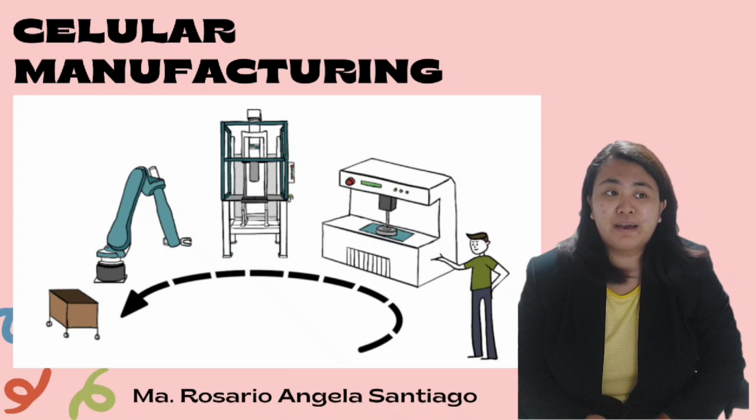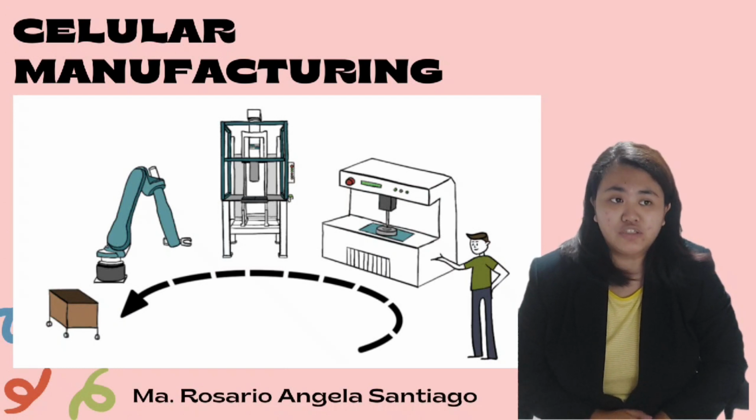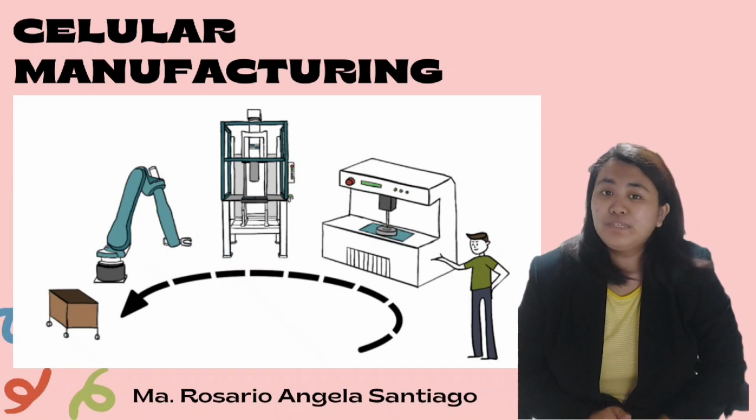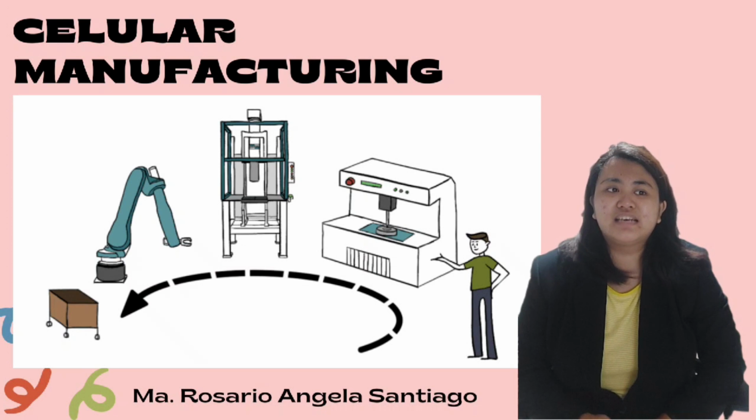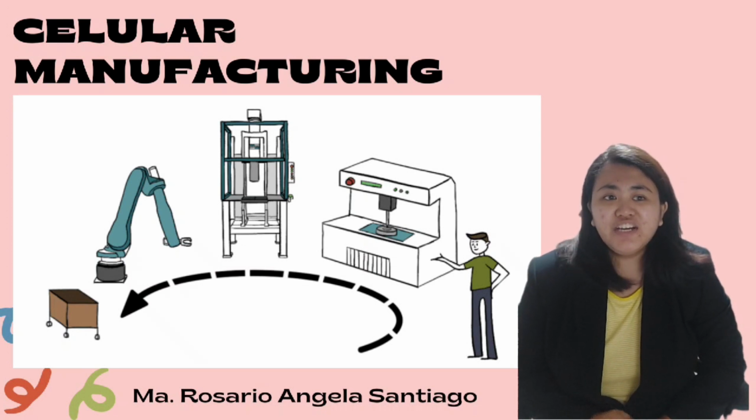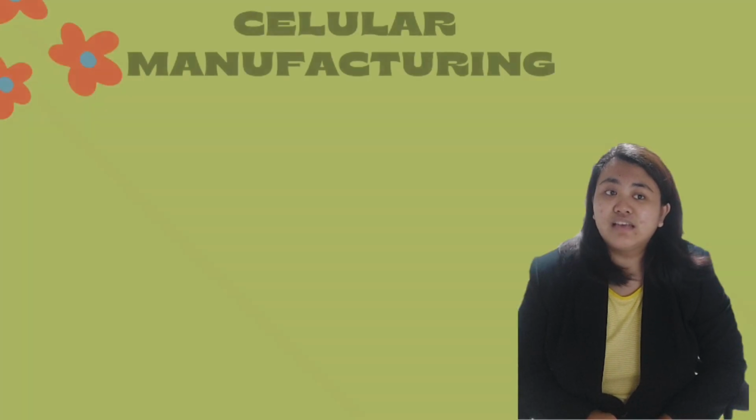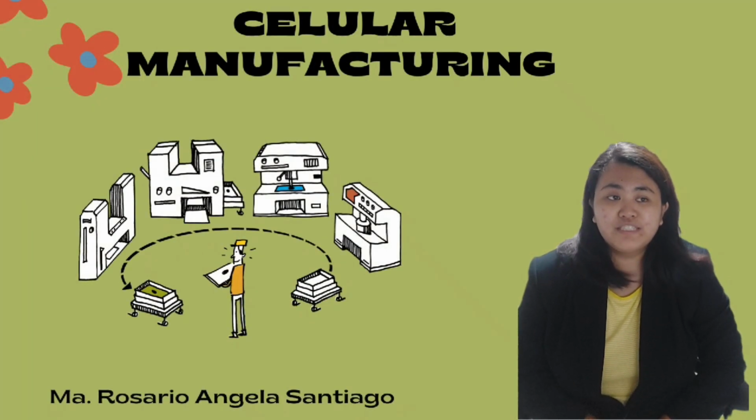Flow manufacturing demands a single-piece flow methodology. This is also called one-piece flow or continuous flow manufacturing. It is a technique used to manufacture components in a cellular environment. Here, the production workstations and equipment are arranged in a sequence that supports a smooth flow of materials and components through the production process with minimal transport or delay.